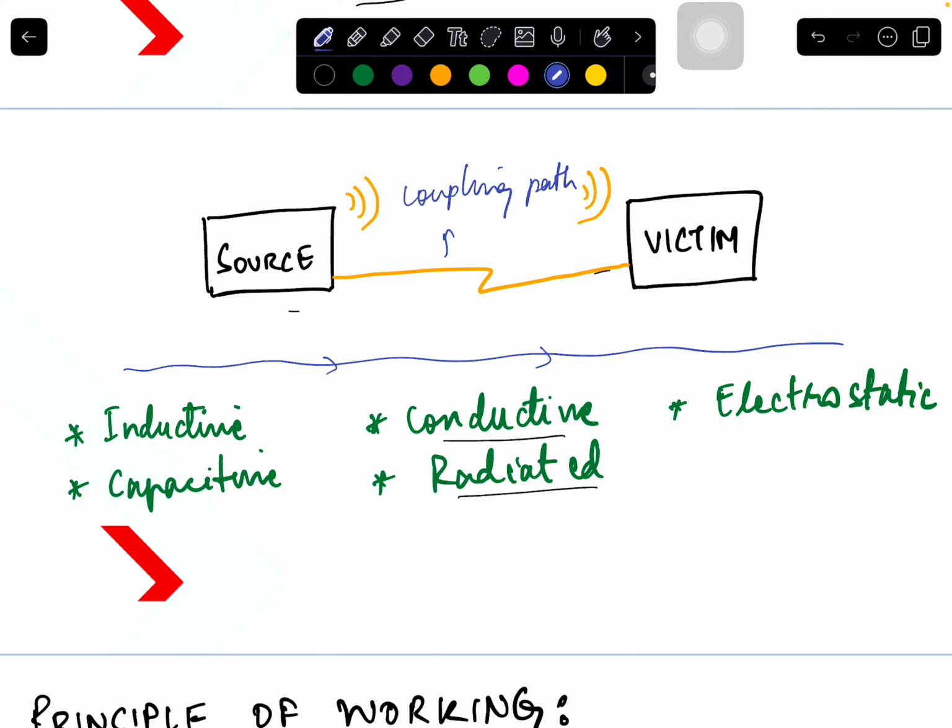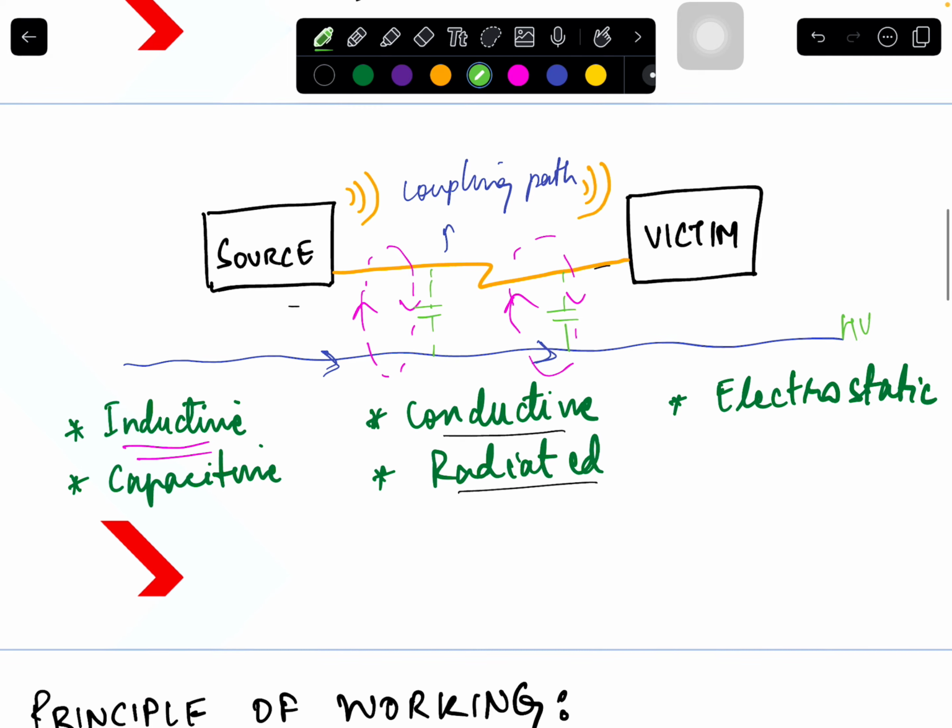So there is a cable that is carrying a high amount of current. Basically, let us suppose it's an AC current. This can induce voltage through Faraday's law in your cable, and this can cause problems. So this is inductive coupling. Capacitive coupling will be when you have a high voltage cable, so it can cause extra high voltage cables to couple capacitively to the nearby ones. But we'll be going into detail on the math behind it and basic models to understand.